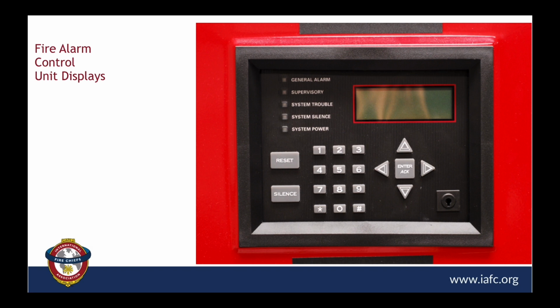So that bottom light is the one I'm going to talk about first. The system power on light is the one that should always be on. If the panel is in normal condition and everything is working good, such as you're there doing a pre-fire visit, or you're there on an EMS call or something, and you look at the panel, the only light that normally should be on is the one for system power. That's letting you know that everything is fine and normal.